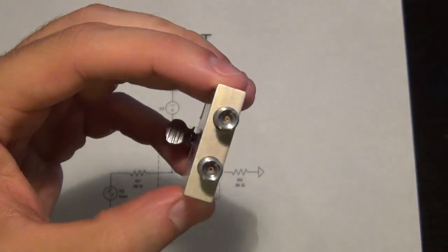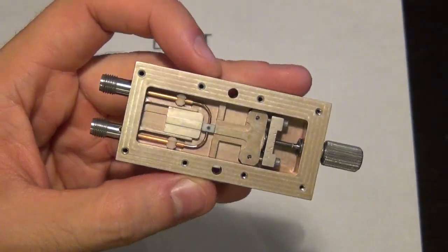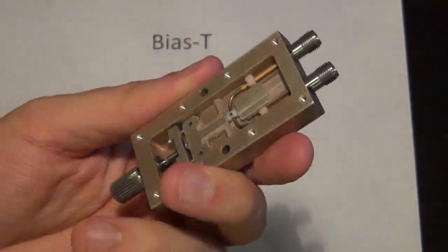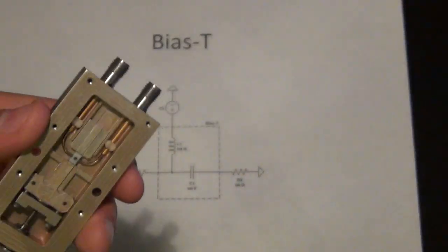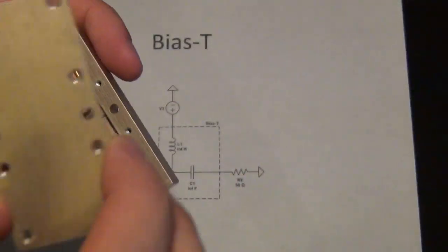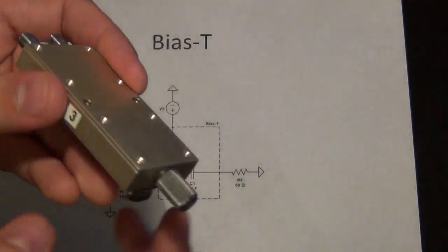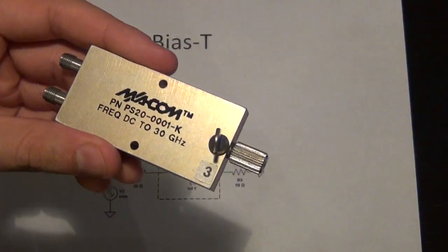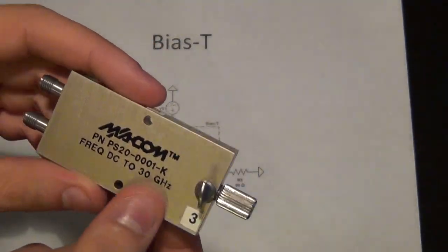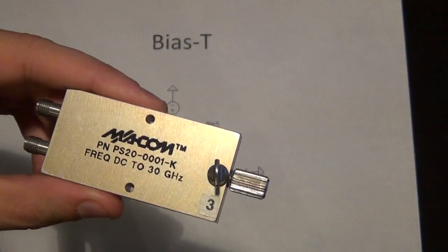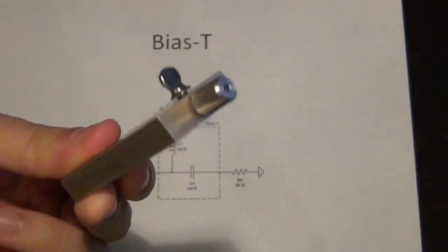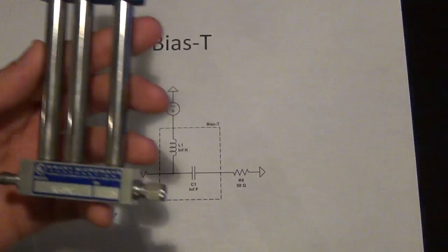But this is a very high frequency one. You can see it uses K connector. It works all the way up to 30 gigahertz. This is a very common way of making phase shifters. These things are very useful when you're dealing with broadband circuits, when you need to align, for example, a clock to a data, or you need to align two signals together. If you want to create a specific phase offset at a certain tone, these things can be used for that.